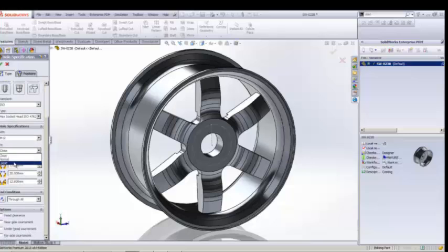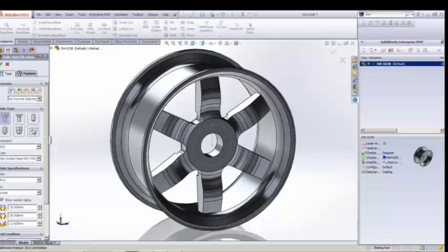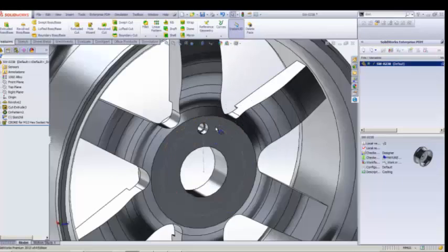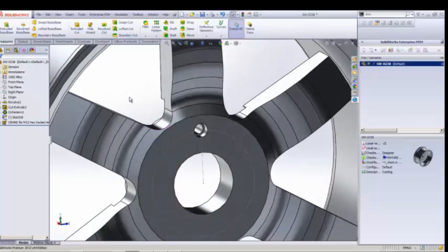Let's specify what is the size and the end conditions that we want. Let's go to the position part of it. Okay, let's go and say position, and let's say 3D sketch, and let's place the hole that is desired. Once the hole is placed, I just need to do a circular pattern for that hole as well.